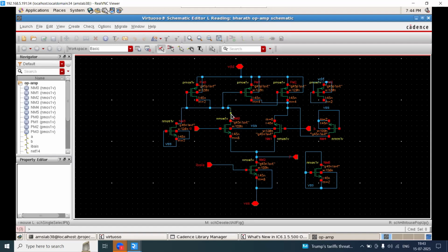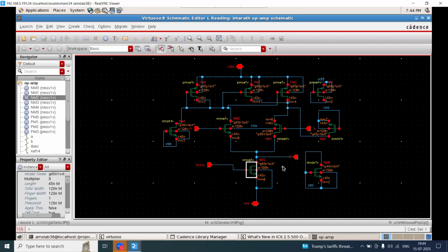These two devices will compare the signals with the same number of routing, same length of routing, and commonly compare and give you the output here, where you will get the output as Y. Before going to process with respect to Y, we will have one NMOS tail device, where the gate is given a bias connection, an I bias reference current.